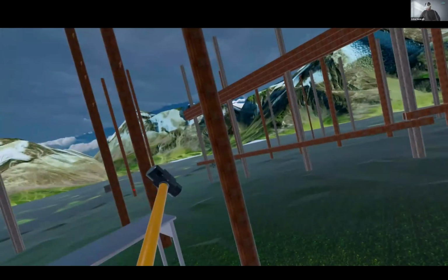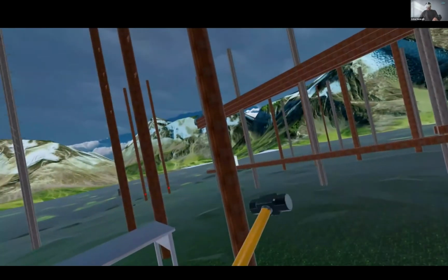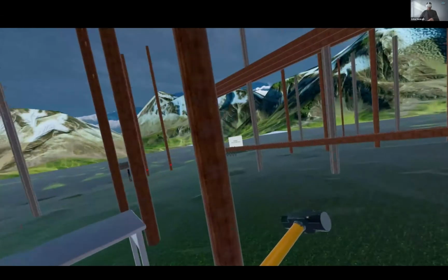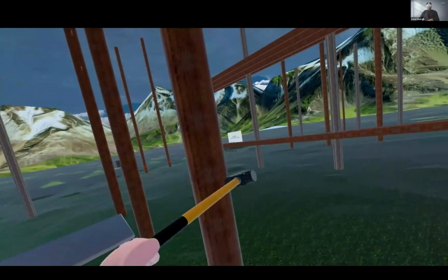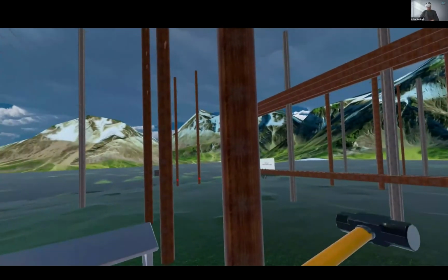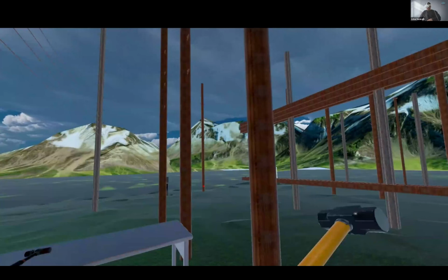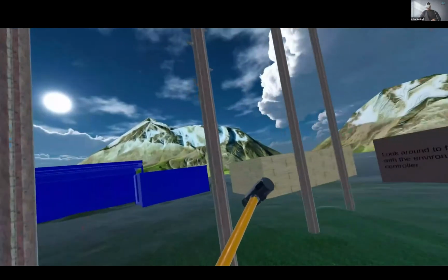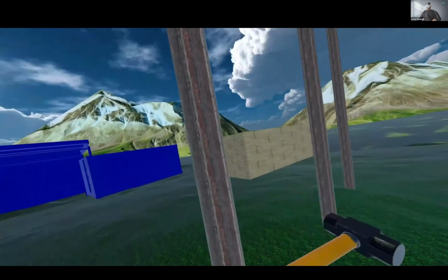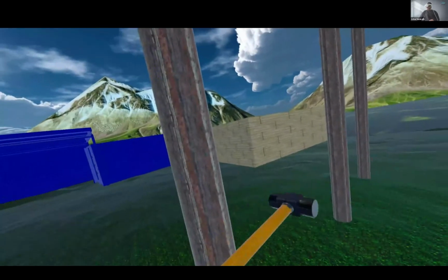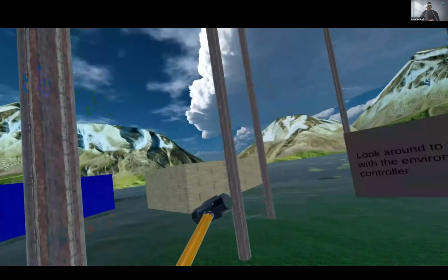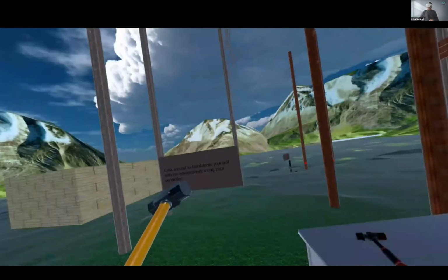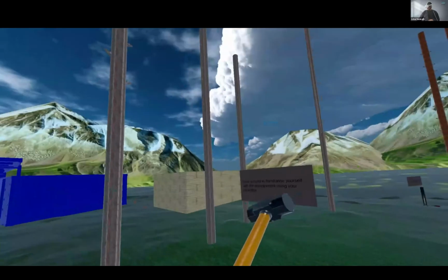If you can hear the voice, it's a rigid sound on the good pole, and if you go to the other side of the pole, you hear a hollow type of sound, which resembles that the pole is not safe for climbing.